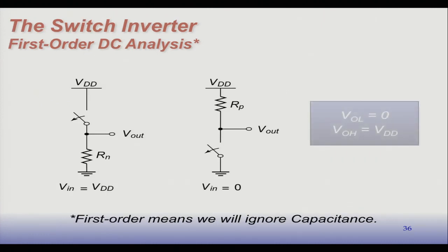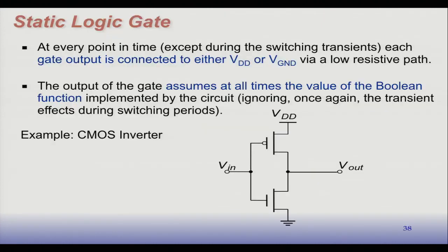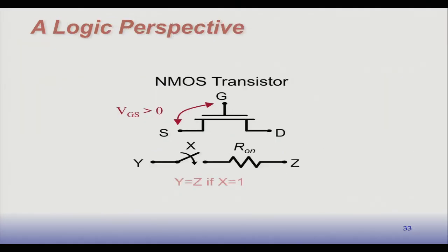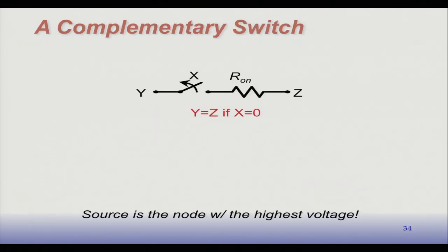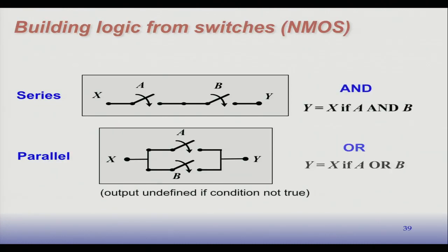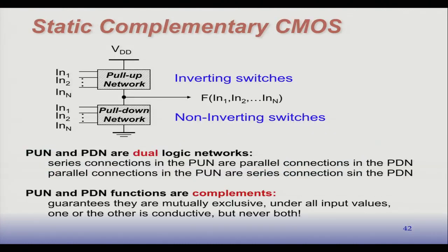And the type of circuits we're talking about were so-called static CMOS. Okay, so the circuits look like this, and this is a description of a single CMOS logic gate. The simple ones you probably have seen already, like NANDs and NORs and inverters, but we said we can actually implement any logic function in a configuration that looks like this, where there's a pull-up network and a pull-down network.